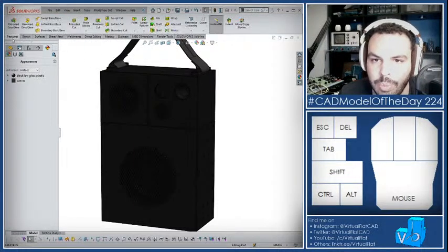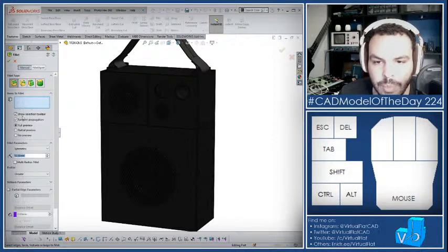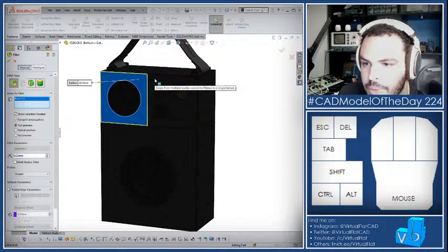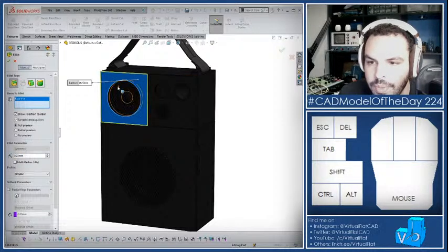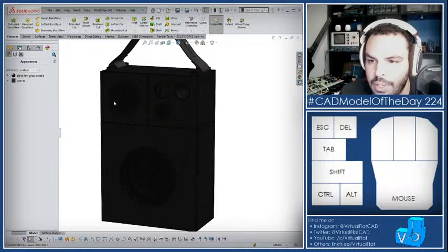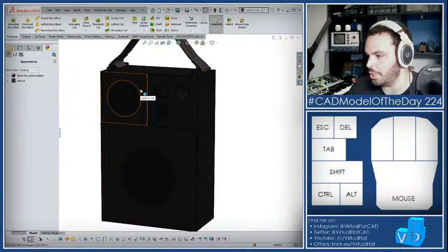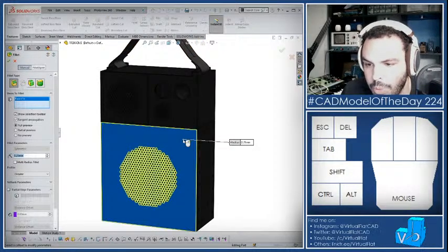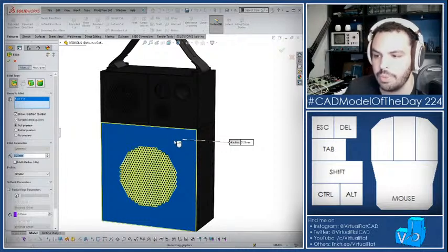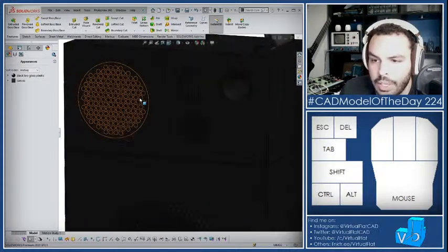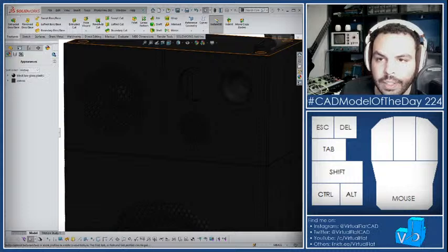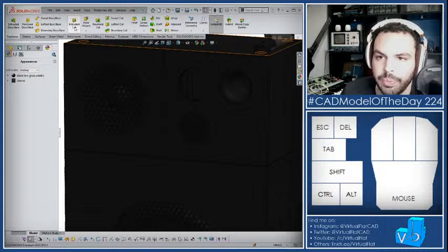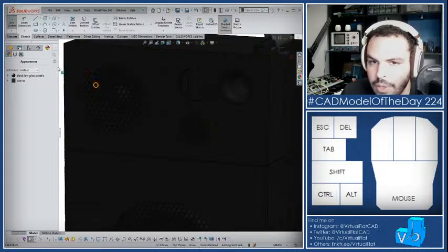I'm going to try and apply some microfillets. And microfillets are the natural imperfections that happen within materials. So there's no such thing as a perfectly sharp corner. And so if you have perfectly sharp corners in your render, that's a lot of edges. Let's see how this does. All right, not that bad apparently. If you have perfectly sharp corners, it can actually remove some of the realism from your renders.